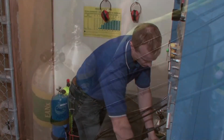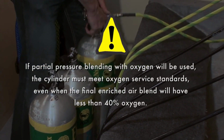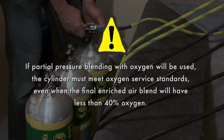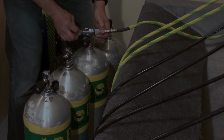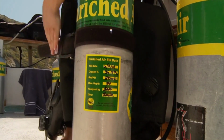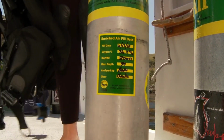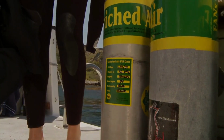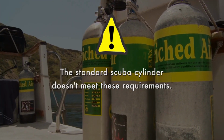This is called partial pressure blending. If partial pressure blending with oxygen will be used, the cylinder must meet oxygen service standards, even when the final enriched air blend will have less than 40% oxygen. This means being cleaned and lubricated for oxygen exposure, and all O-rings, gaskets, and other valve materials must be oxygen compatible. The standard Scuba cylinder doesn't meet these requirements.